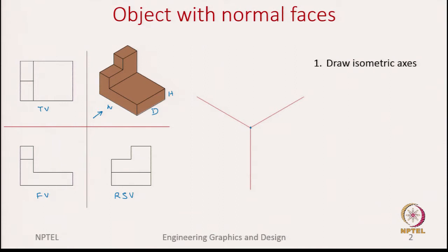So, we start to draw this object using this corner point which is placed here. Okay, let us label it as O for convenience. Now, what we do is, for example, if I want to capture this front view, especially this face, should I do it to the left of point O or to the right of point O? So, that should be captured to the left.